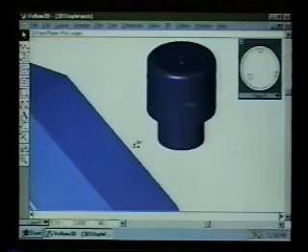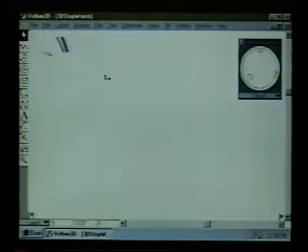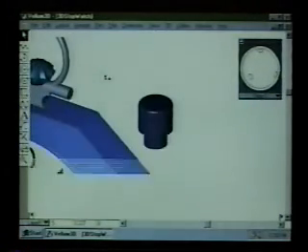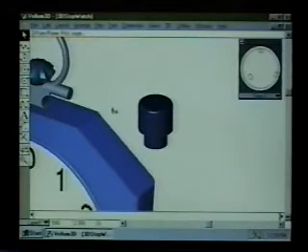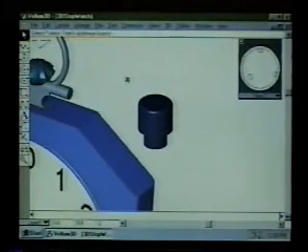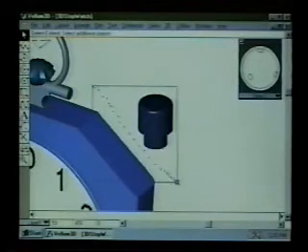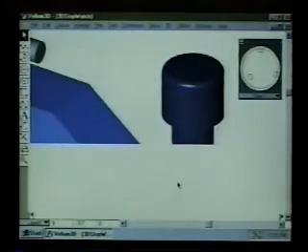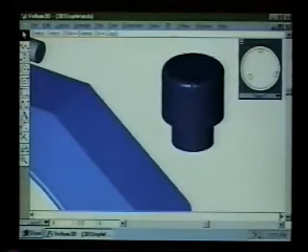In fact, we'll back out just one time here. All the objects are showing for now, but I can define a new plane that would, for example, start at the midpoint, and that would be the origin. The X direction would go off in this direction, and the Y direction would go off in that direction, and my triad now shows tilted back to match that. So if we zoom back in here just for ease of working with this, now I can select this object, and I can move it into position with the help of the drafting assistant.